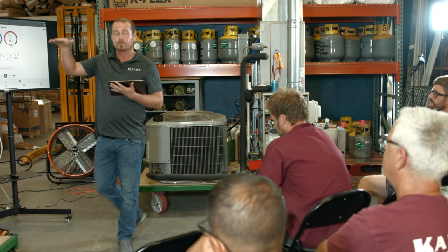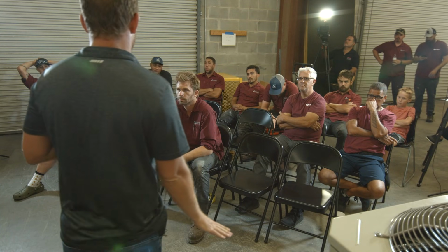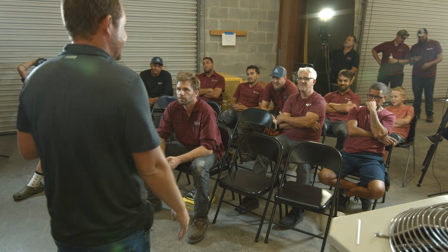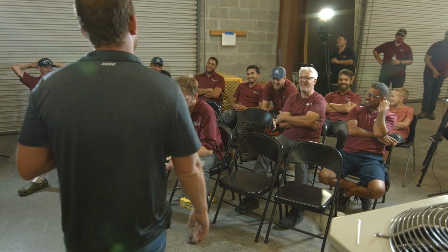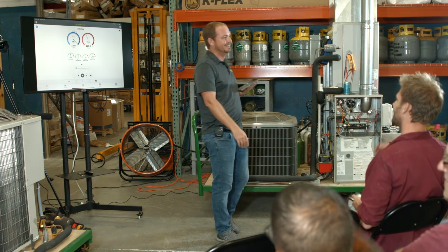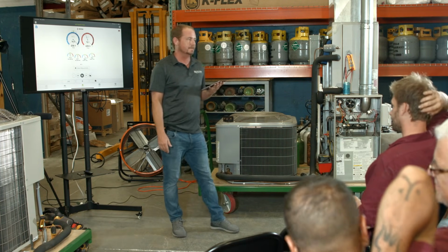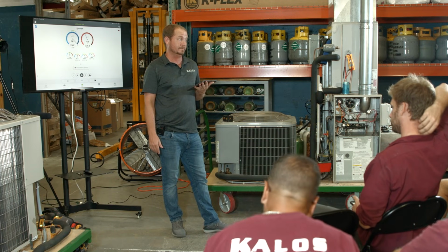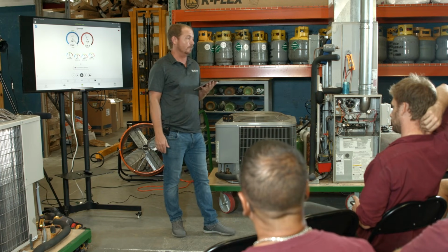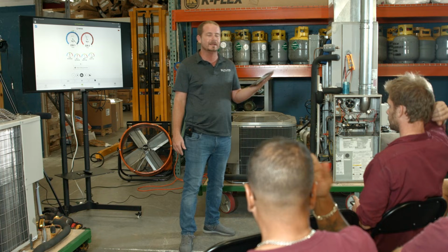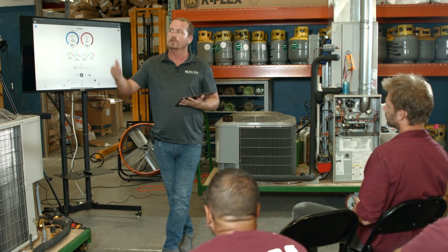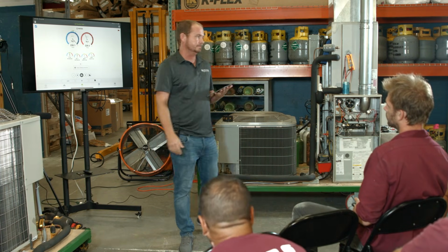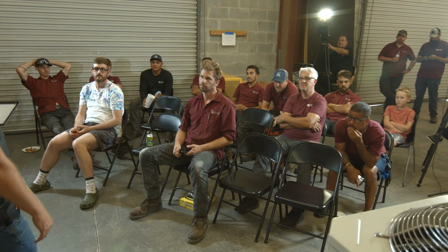What's going to happen to your compressor when you have low airflow? What's going to happen to your compressor? Amp draws. Amp draws what? Drop. The amp draws do drop. Why does the amp draw drop when you have low airflow? It's doing less work, right?